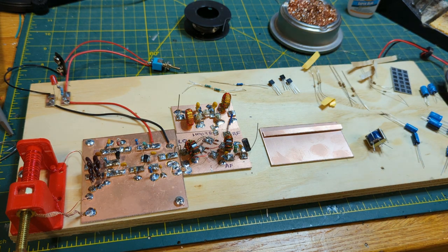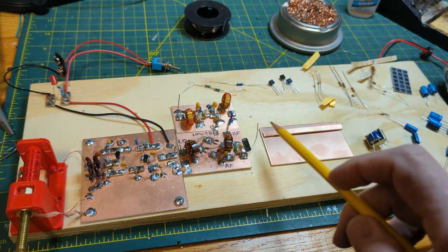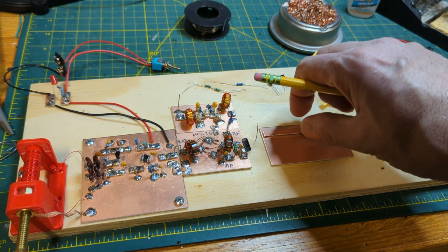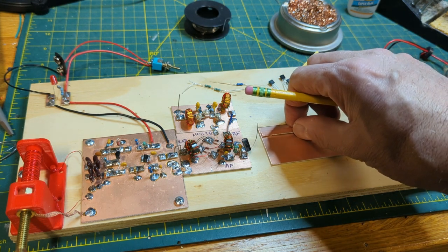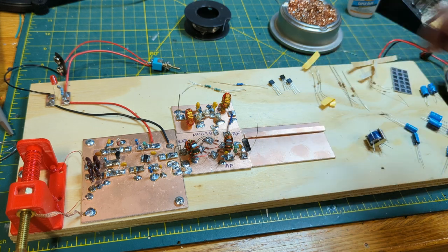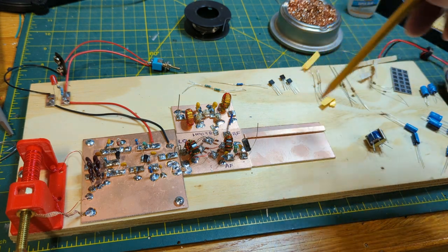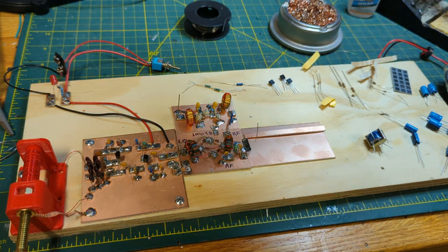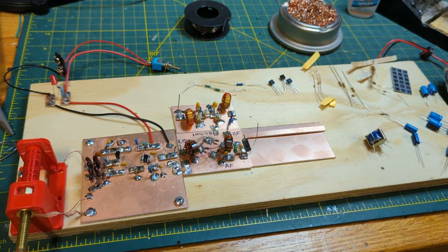If you don't do that, you can use individual pads and just jumper them together, but for convenience, I'm going to use one long piece, and that'll be our 9-volt rail. I'm going to put it down a little bit on the board just in terms of construction technique, because I'm going to put the bypass capacitors to ground on this side just to keep them physically away from the rest of the circuit, so that I can have enough room to build the rest of the circuit.